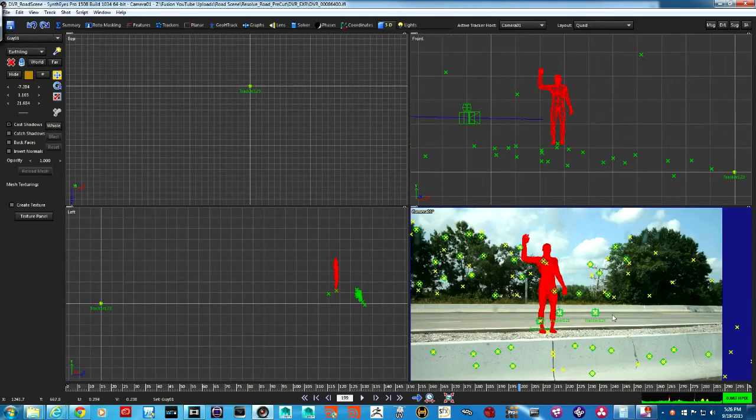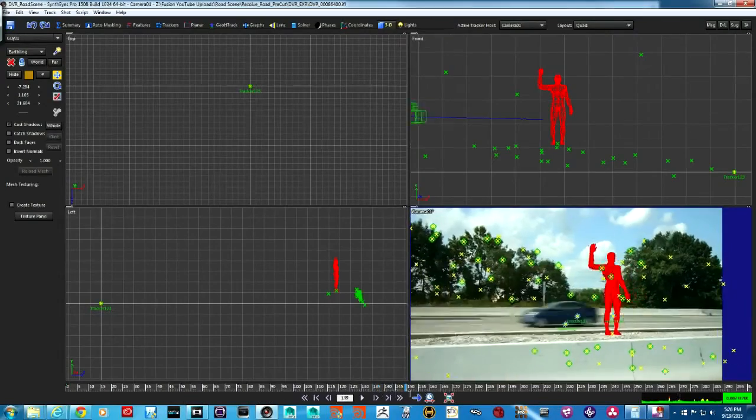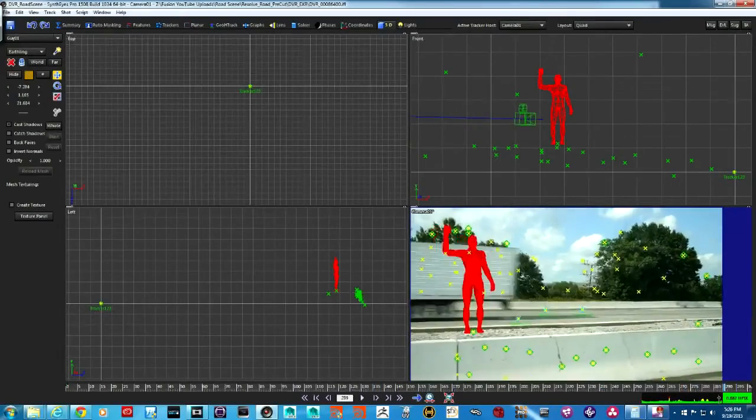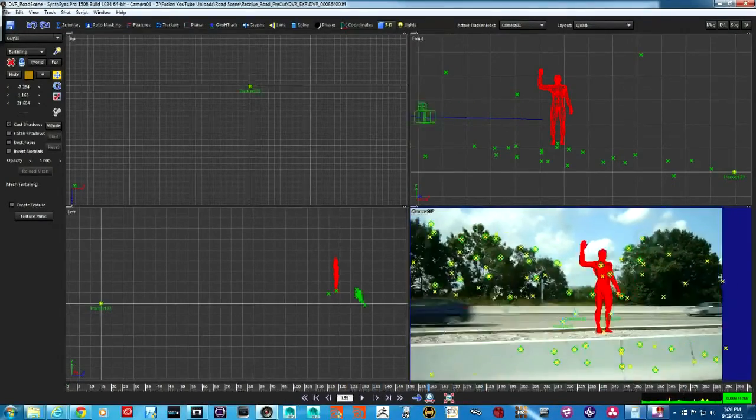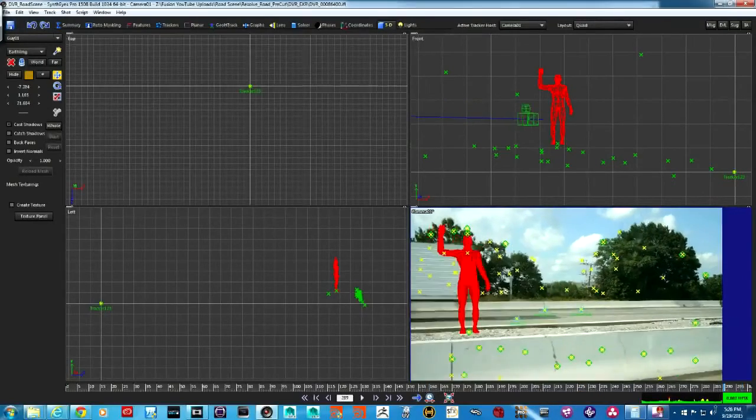I would have done the supervised tracking rather than automated tracking, and in that case I would have picked similar track marks to this one that I picked, and I would have probably picked other track marks to complete the whole scene and deleted all these other track marks that we have. Anyway, that's for some other day, but for now I think we can use this track. It seems relatively solid, so we can really fix the objects onto the plane.